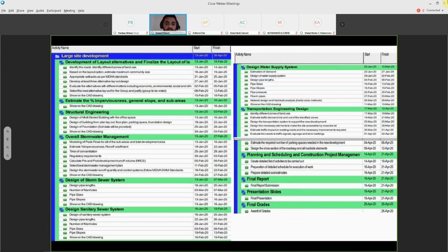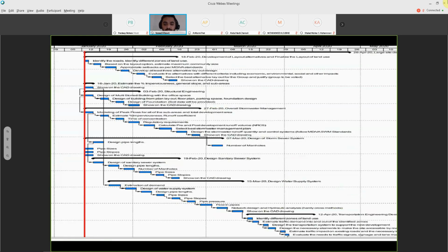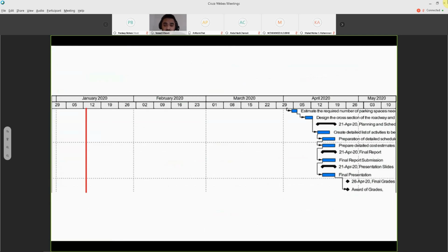So this sheet shows our planned activities used by Primavera P6. All the activities were linked with each other using start to start or finish to finish logic. If one task gets delayed because of some reason, all the following tasks will also get delayed, and our project will ultimately be delayed. The software helps with calculating the delayed date of the finish. Second slide.